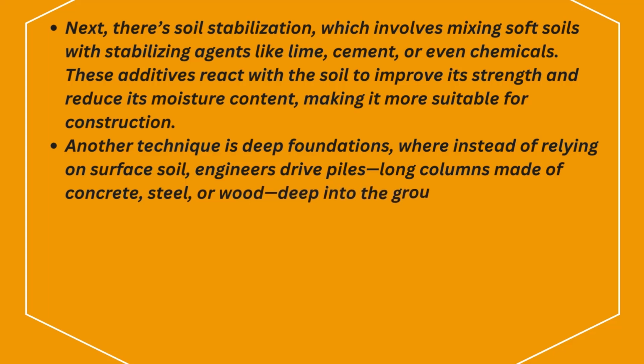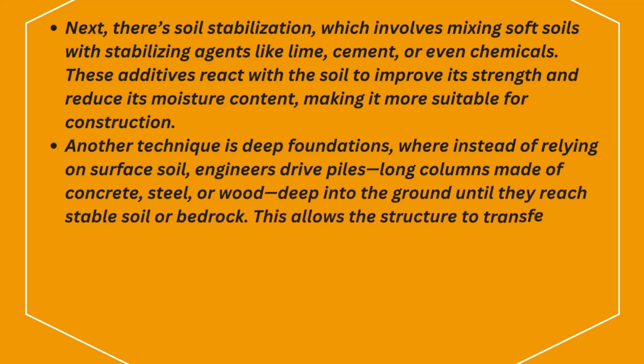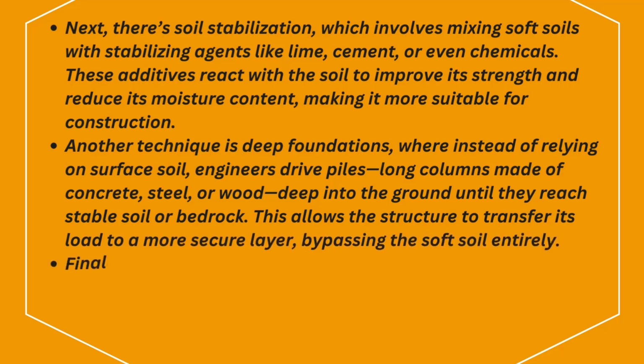Another technique is deep foundations, where instead of relying on surface soil, engineers drive piles, long columns made of concrete, steel, or wood, deep into the ground until they reach stable soil or bedrock. This allows the structure to transfer its load to a more secure layer, bypassing the soft soil entirely.